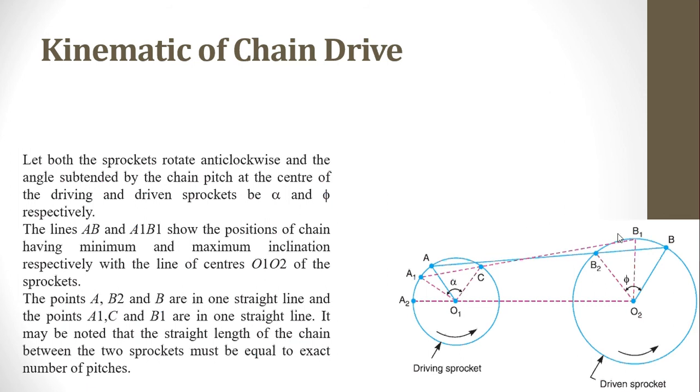So the chain drive is an assumption of a 4-bar mechanism. In fact, it's a 4-bar crank mechanism. So with the 4-bar equations, you can also solve for the velocities and accelerations.